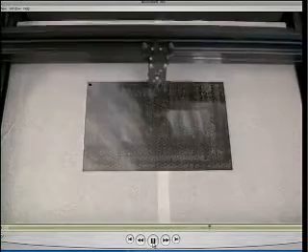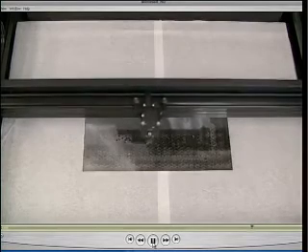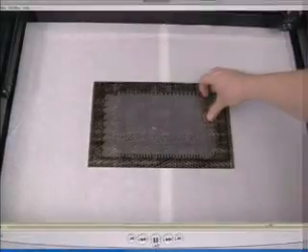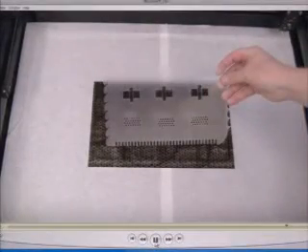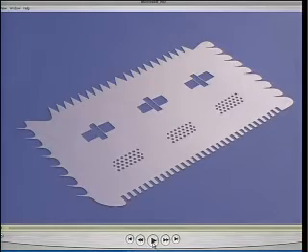What's that material you're using as a vacuum? It's tape. That's just transfer tape, covering up the open space in the cutting table, so that the vacuum from the exhaust holds down our material. So that's the final material, and we actually did that for all the films that we found, prism film, and I think this was the anti-glare film, and a polarizer film. So it's useful for cutting any of the thin film materials within the display.